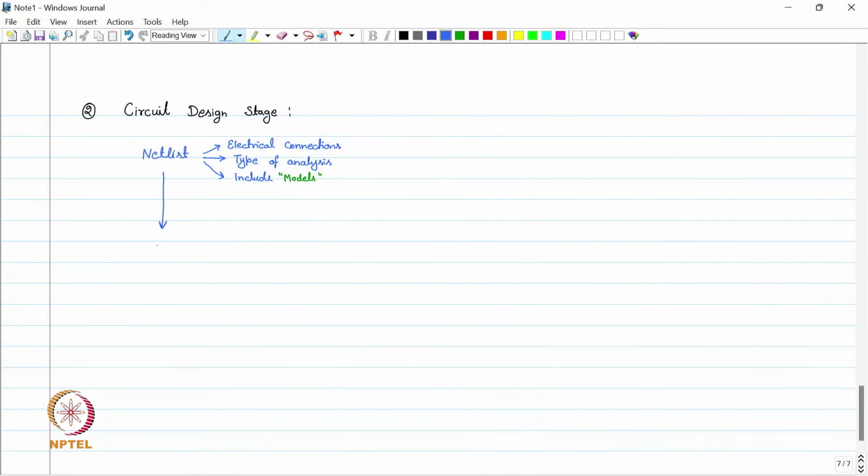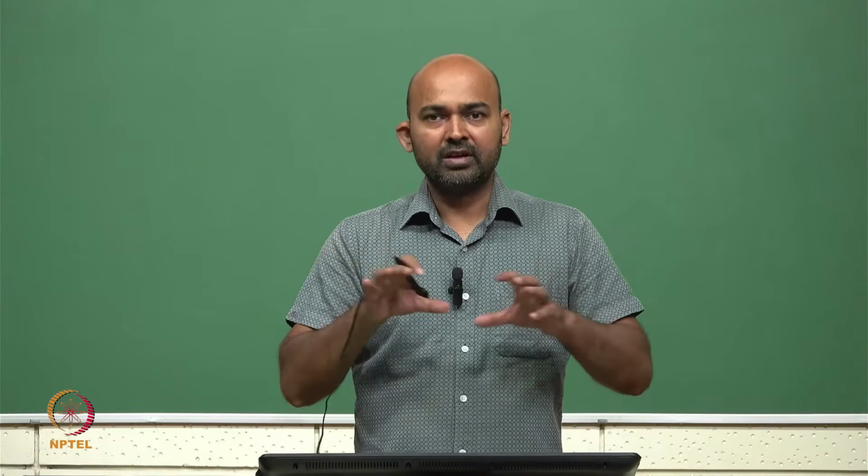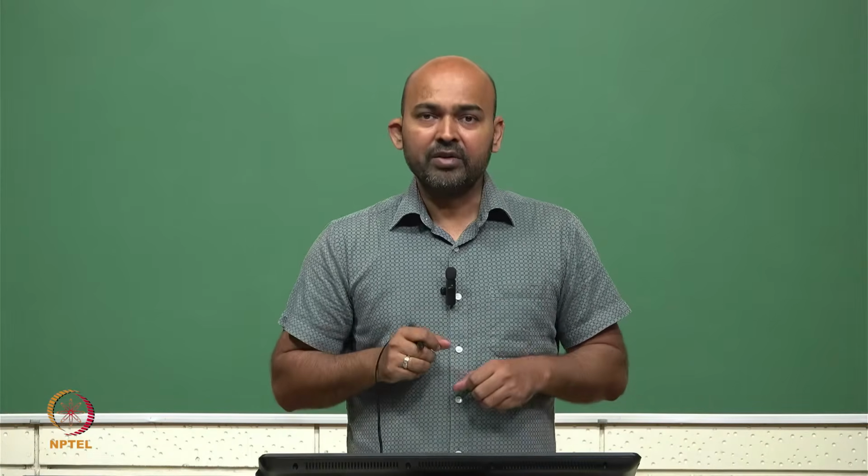This net list goes to a simulator called SPICE, which can solve these equations and prepare the electrical voltage and current at the nodes. So the SPICE simulator is nothing but an algorithm which solves all of Kirchhoff's laws and continuity equations using these models and finds all the node voltages in that circuit.